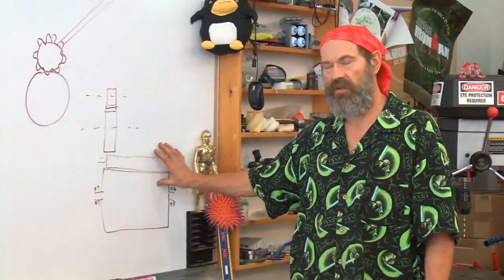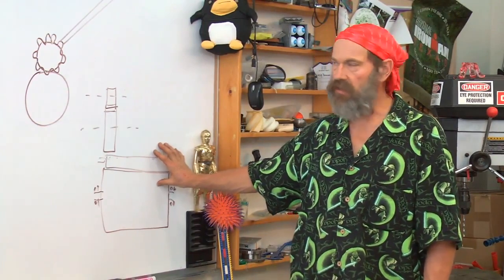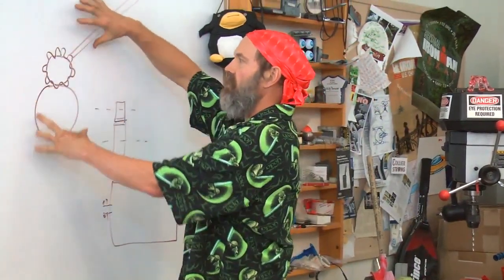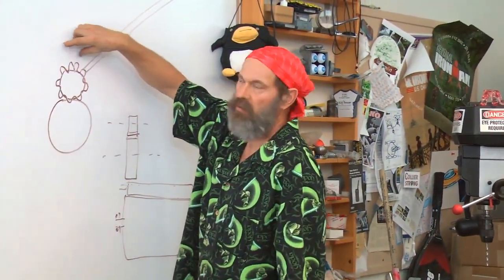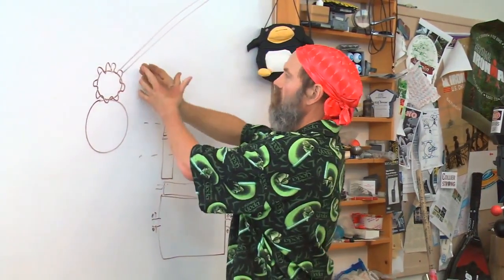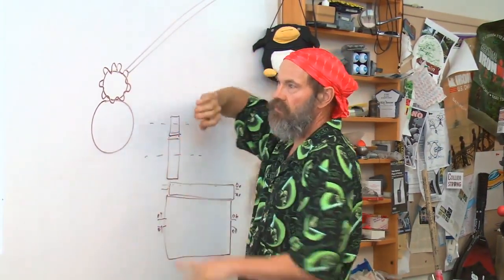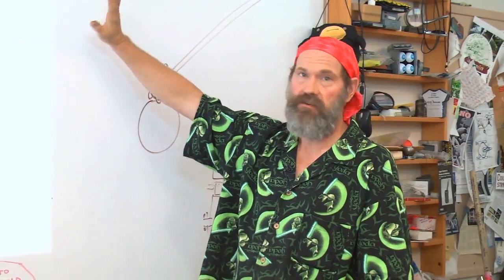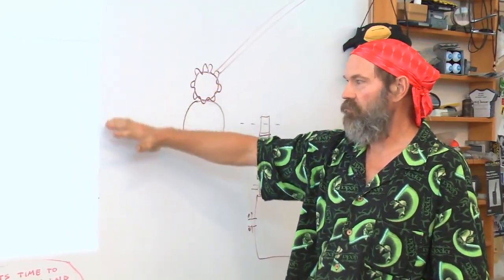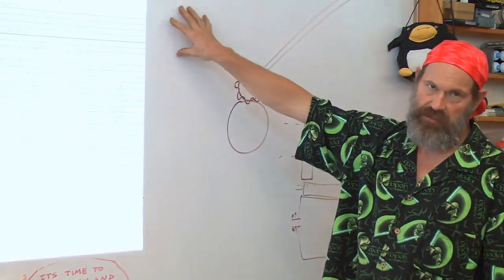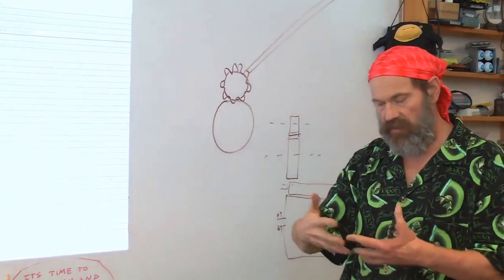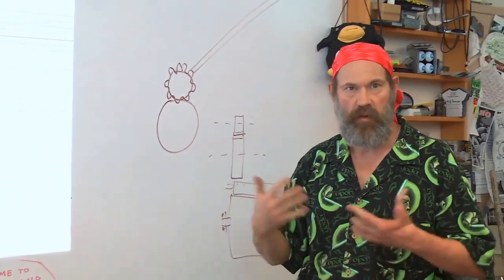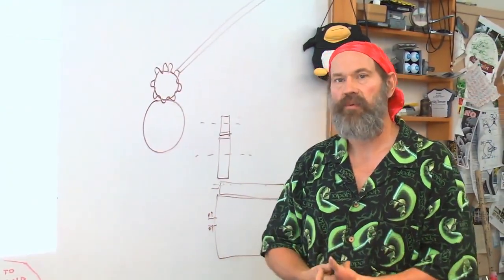And the way you're going to want to transmit the high loads you're thinking of is you have to make the gears bigger and the teeth bigger, rather than just keeping the teeth arbitrarily small and the gear really wide. So this design spreadsheet, spur gears, for example, helps you go through all those inputs and outputs and sizing your gear and telling you what the separation forces are so you can incorporate it in the design of the shaft and the bearing supports.